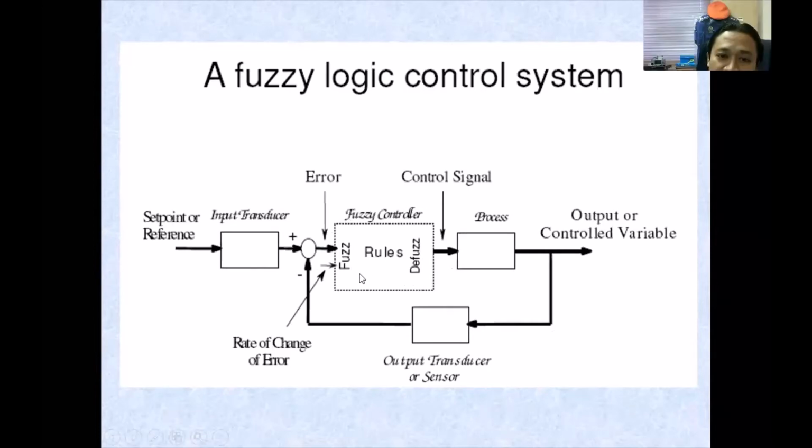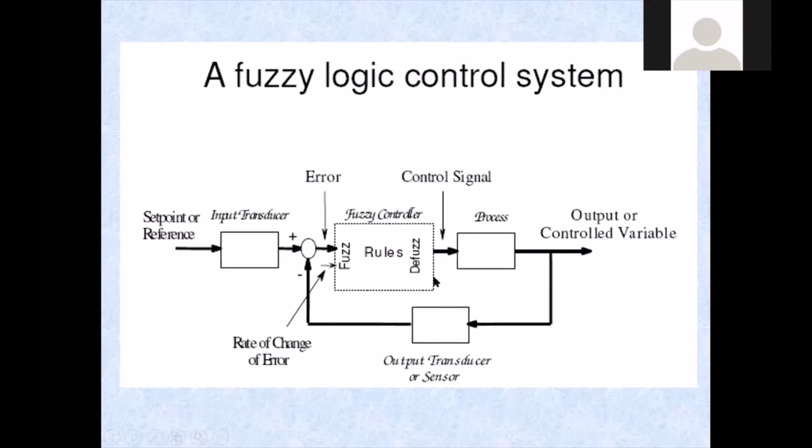After this we go for the components inside the fuzzy logic. Actually, in fuzzy logic we have 4 basic components, you can see this one. We have the fuzzification or fuzzifier, then the inference engine, the knowledge base, and the defuzzification. So these will be inside the fuzzy logic. We have 4 main components for the fuzzy logic.